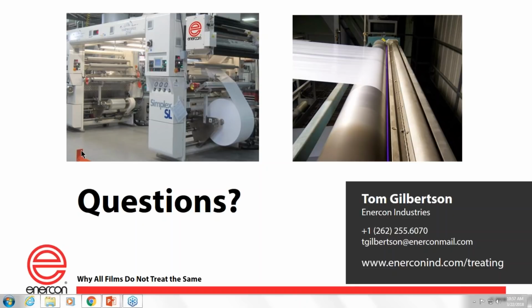Now take the same example. Let's say we have the exact same machine. We're going to try to print Teflon film. Well, corona treaters don't do very well with Teflon film generally. So in that case, an atmospheric plasma treater actually would make a lot of sense because the atmospheric plasma treater has the ability to change various gas chemistries, add and delete things, which therefore give you a discharge that's more suitable for working with this PTFE surface that we're now dealing with.